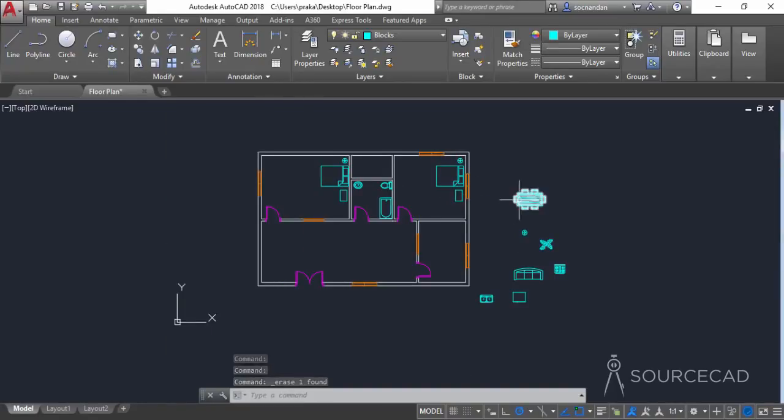Now let's add this dining table. So select it, select the move tool, and place it over here. We'll rotate this one as well. So select, rotate, and rotate it to this 90-degree angle, and I may need to move it because we accidentally selected some other point. So there we have it. Alright, now let's add these objects in the drawing room. So I'll select this move tool, and I'll move this sofa somewhere over here.